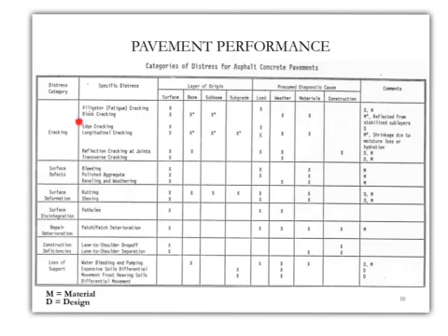Is it a type of cracking, or surface defects, or all the way to loss of support? And then we need to be specific about what type of distress. For example, under cracking, you may have alligator fatigue cracking, block cracking, edge and longitudinal cracking, all the way to reflective cracking at joints.